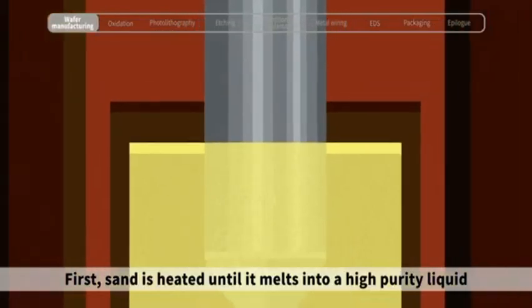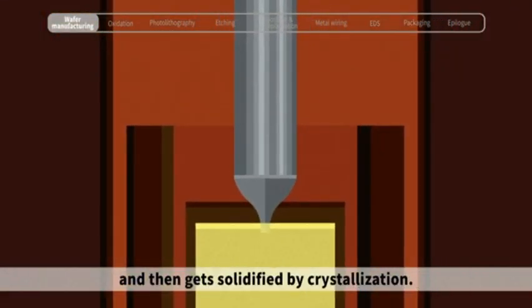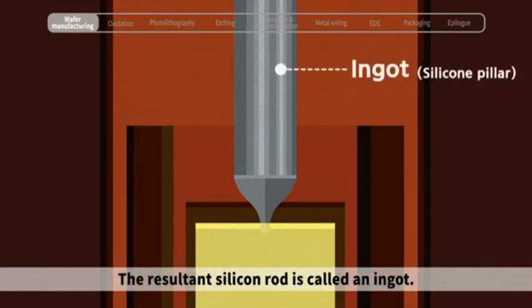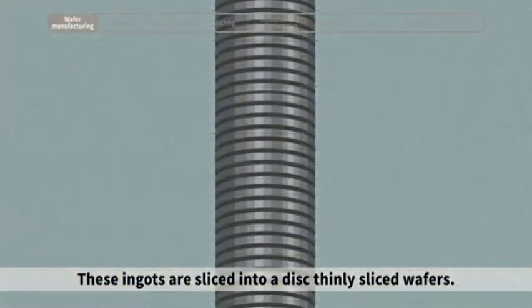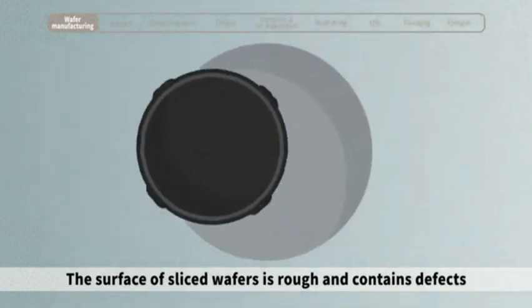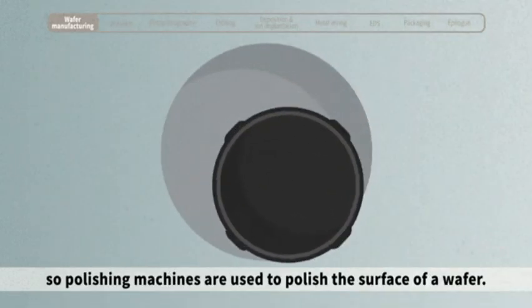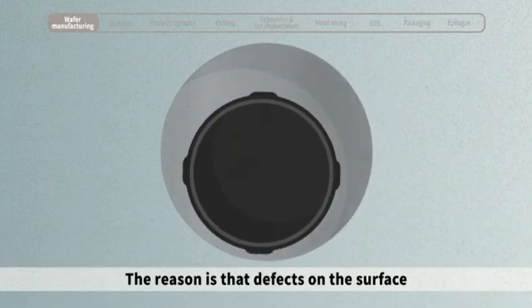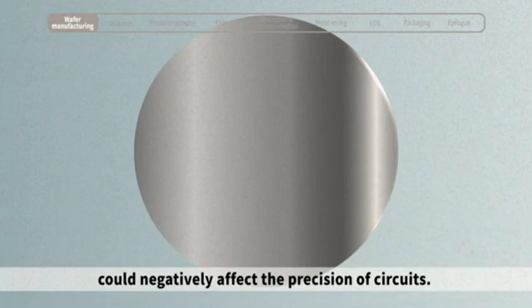First, sand is heated until it melts into a high-purity liquid and then gets solidified by crystallization. The resultant silicon rod is called an ingot. These ingots are sliced into thin, disc-shaped wafers. The surface of sliced wafers is rough and contains defects, so polishing machines are used to polish the surface of the wafer. The reason is that defects on the surface could negatively affect the precision of circuits.